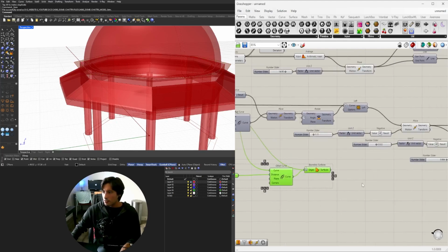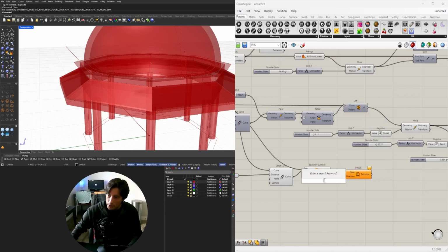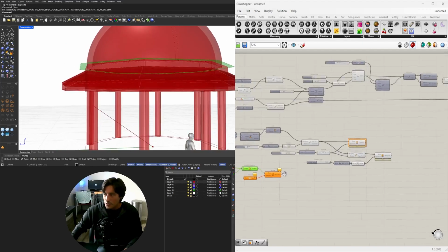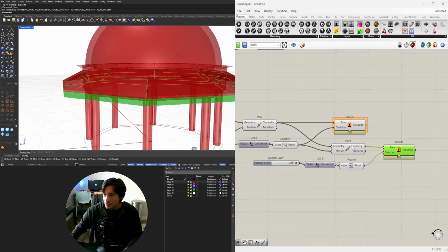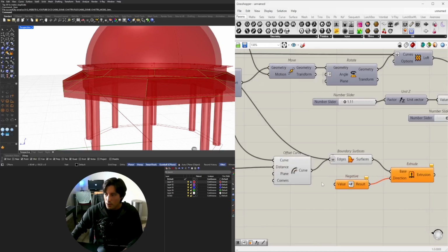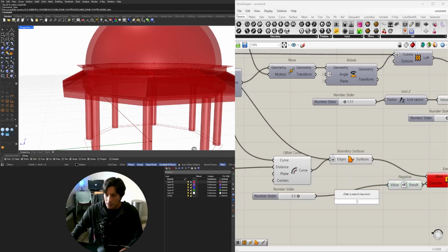Now let's extrude this down. So extrude component in the negative direction or down by the same amount as this, but we can actually use whatever number because this is something that's going to overlap and we can use as a Boolean intersection.